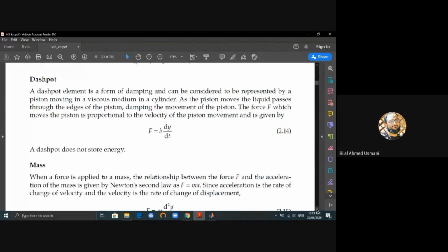So what happens is that immediately the spring depresses, it should release a certain amount of energy. So the dashpot actually damps that release. Immediately the response of the spring is reduced many folds because of the dashpot, because it's usually a cylinder, usually some hydraulic system, so that actually reduces the response of the spring, or the outburst of energy released immediately as a response. So that's why we use a dashpot element.